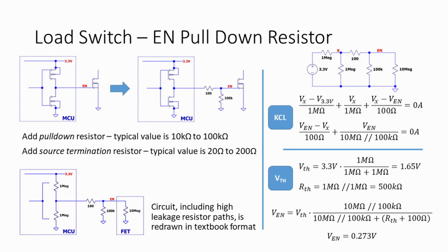And the other reason, and this is specific to PCB designs, is that it separates connections to and from any complex logic devices like microcontrollers and FPGAs. Having a resistor in the path helps with troubleshooting when something isn't working correctly, since it allows you to isolate the components, and it serves a protective function as well.